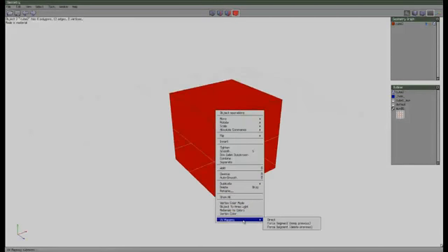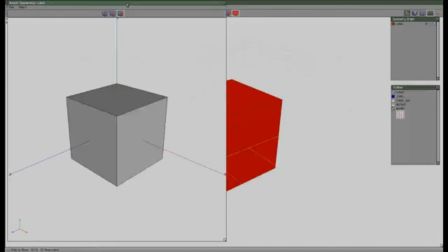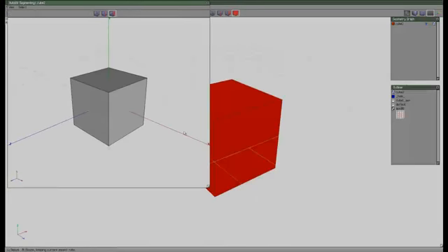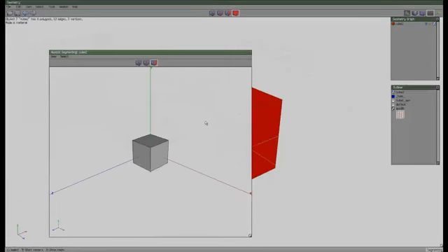And when you right click and go down to the very bottom, you see UV mapping. Now you have three options here, which is direct, force segment, keep previous, and delete previous. I'm going to tell you what that is a little bit later, but for now it's not really important. I'm just going to do direct, and there we go. When you click direct, you get a new window, a new 3D window.